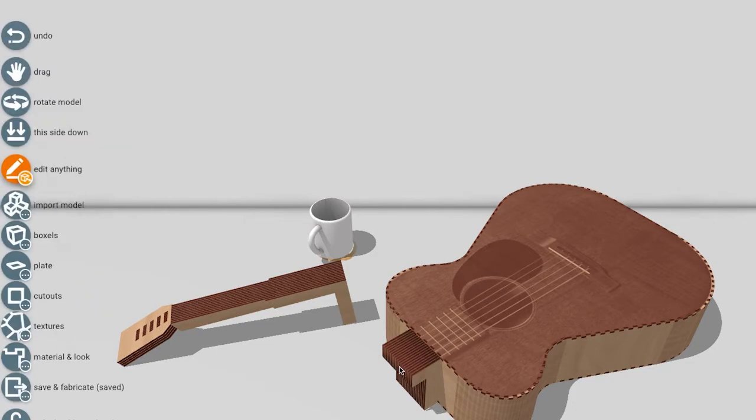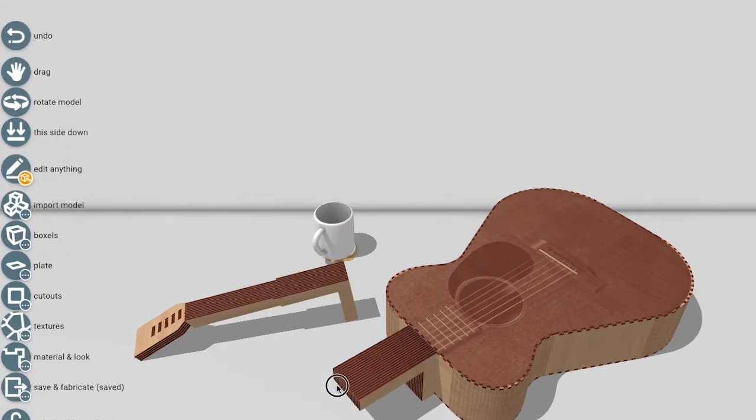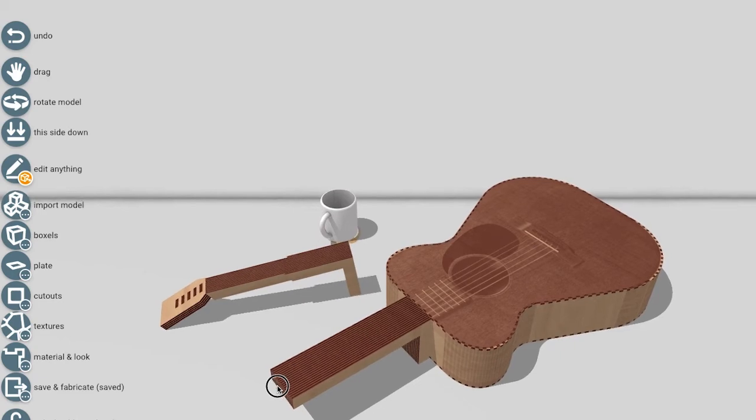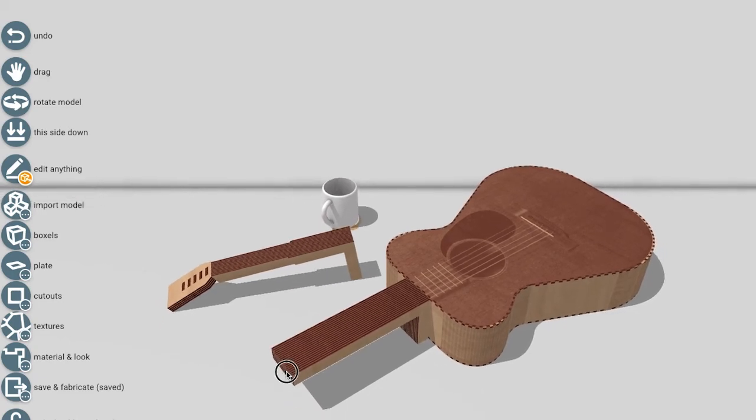To form the neck, I would like it if all these plates extend at the same time. I would like to think of all of these plates as one, so essentially a volumetric element. Our system actually allows us to do that. The moment I attempt to stretch this with the volumetric stretch tool, I modify all plates at the same time. What happened under the hood is that the system recognized that this is similar to a volume, and it thus switches to a volumetric representation.